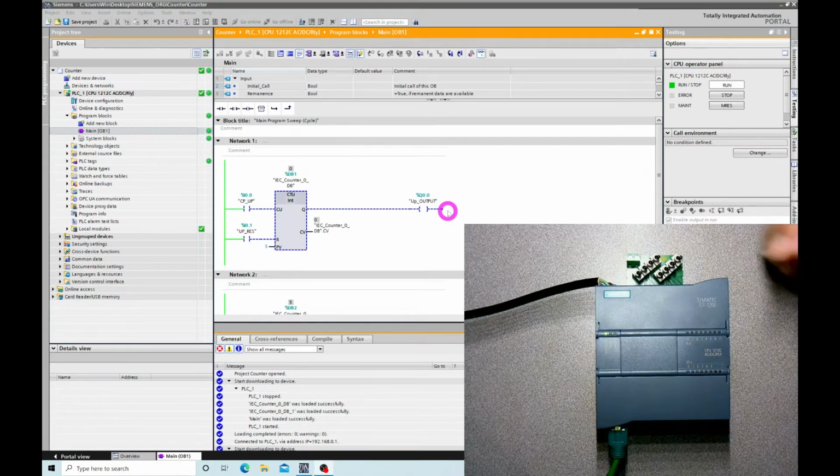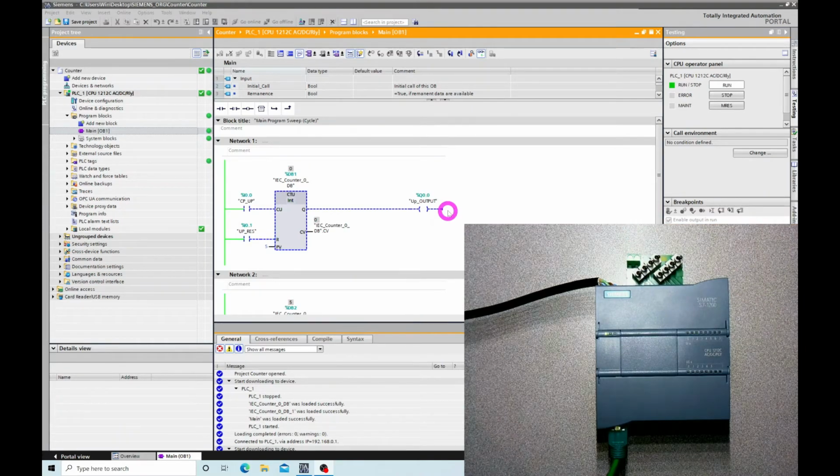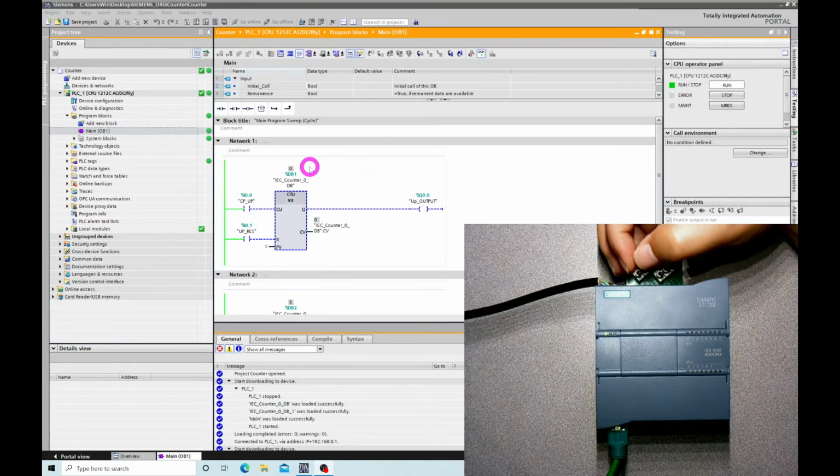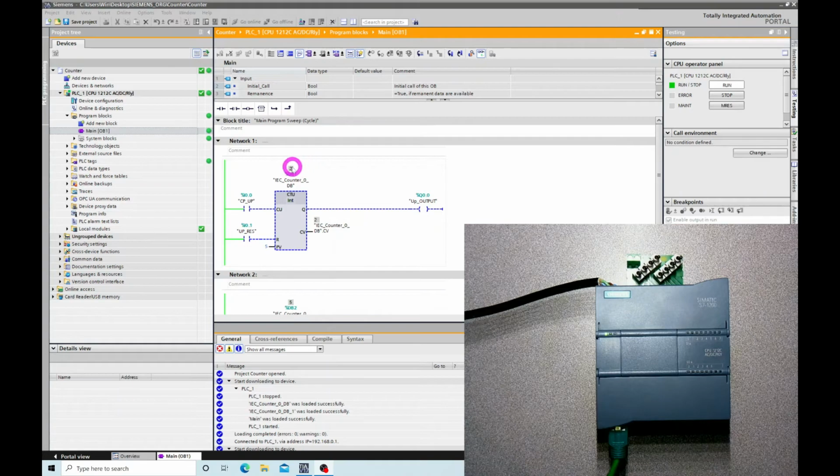As usual, whenever you want to start working with any counter, first you reset it, right? So I activate the reset, which initializes the value to 0 here, which makes sense. Then after that, whenever I push this button, which produces a pulse, it should start to count. So I'm starting, it's 1, I go up, it's 2. You can see these values change, and the current value is 2. And the output is 0 in all of them.